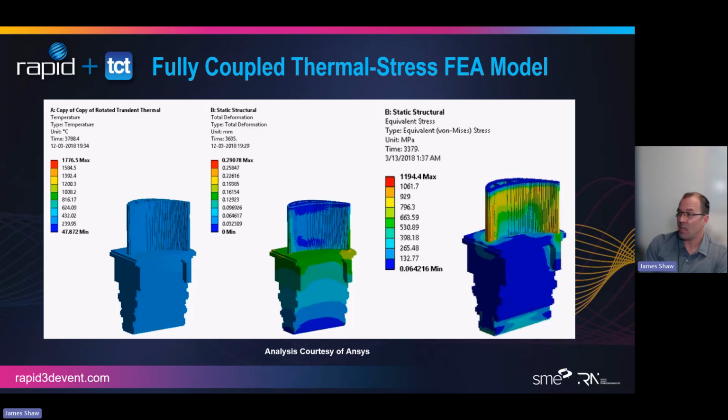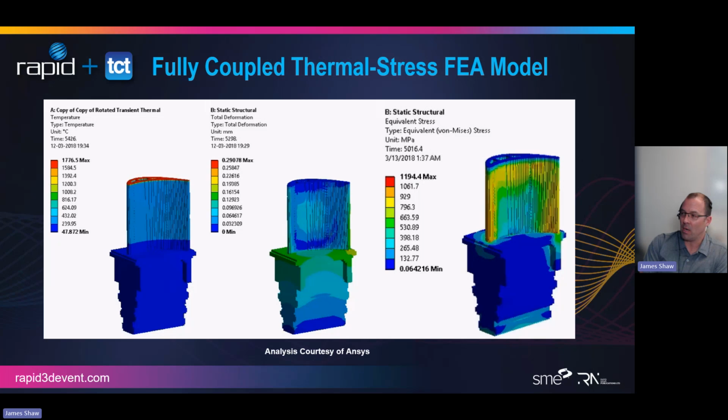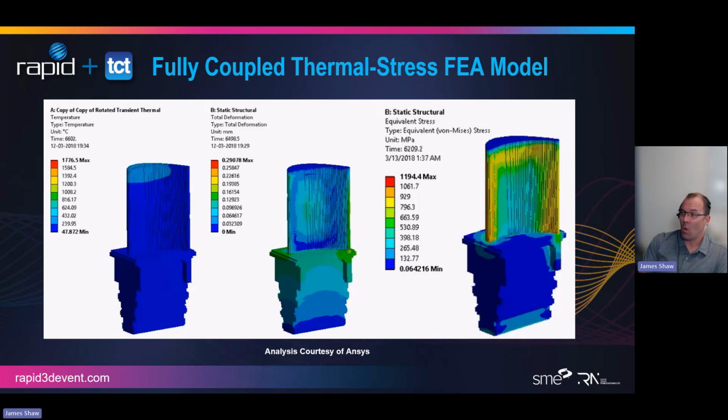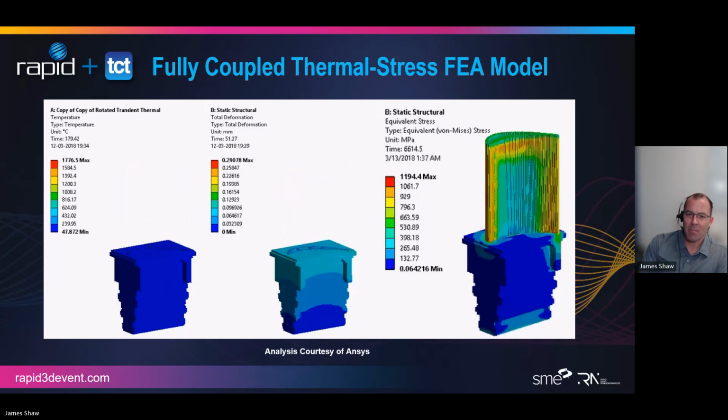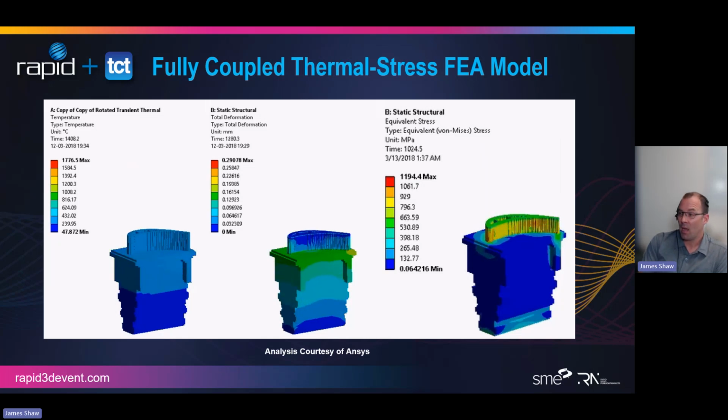The printing process can either be done layer by layer by layer, like a powder bed diffusion, where each layer of material is added very, very quickly relative to the overall print, or a directed energy deposition, AKA sort of a fancy welding process, right? Where we're adding material maybe a slightly slower rate on any given layer relative to the overall print time. This is an animation of a powder bed fusion process.